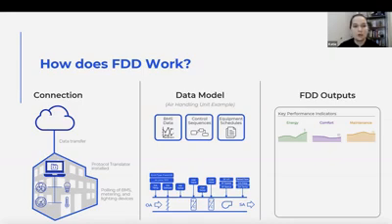So they're trying to quantify these things so that you're not just given an alarm that gives you no information about, do I need to act on this or not? It just says, go do it. It's giving you a little bit more information so you can prioritize your work. And then it'll say, okay, of those, these are the top things, right? So if energy is very important to your campus, these are the top things that you should be responding to: the simultaneous heating and cooling fault, this economizer override fault, and this reset sequence.